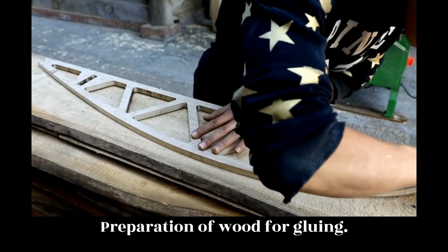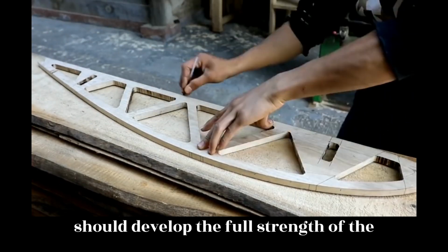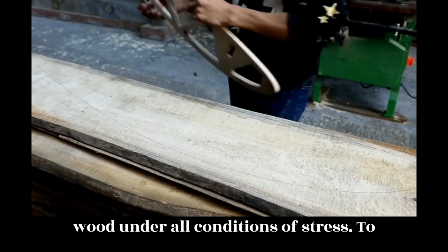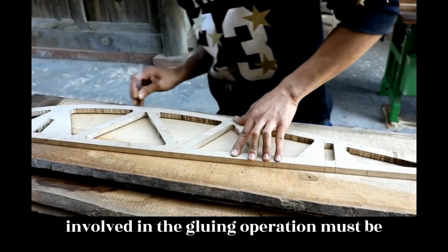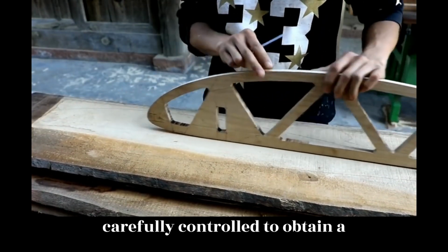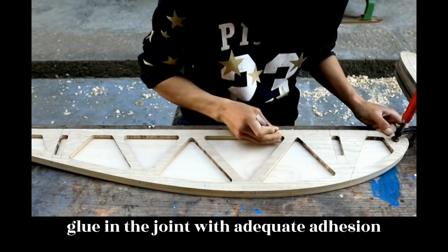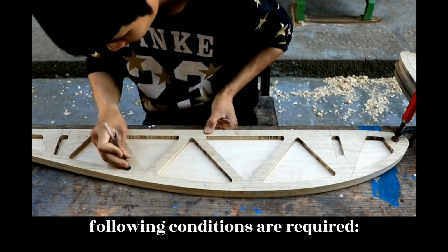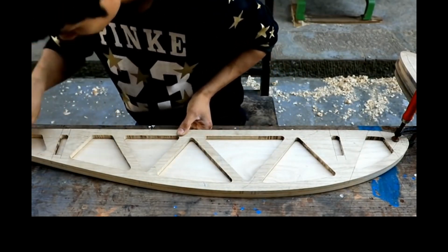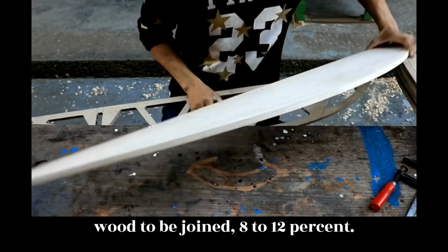Preparation of wood for gluing. Satisfactory glue joints in aircraft should develop the full strength of the wood under all conditions of stress. To produce this result, the conditions involved in the gluing operation must be carefully controlled to obtain a continuous, thin, uniform film of solid glue in the joint with adequate adhesion to both surfaces of the wood. The following conditions are required. 1. Proper and equal moisture content of wood to be joined, 8 to 12%.